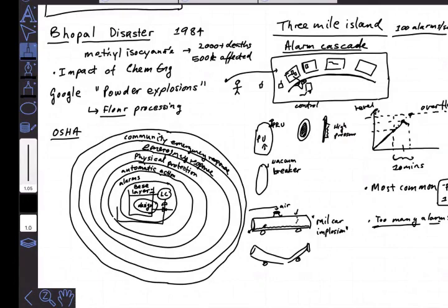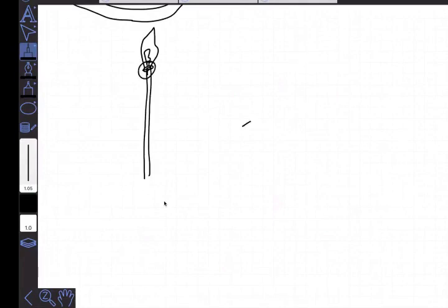So most flare systems are simply valved. In other words, they are actuated. It's like you would put a valve in here, except that valve goes into the atmosphere. And then the flare system itself, in order to actually make it a flare, and maybe for those of you who are not familiar, if you've ever been to Sasol, you've seen these very, very tall towers, and then there's this massive flame here, right? Now, if you think about how that actually works, there's a whole ignition system.